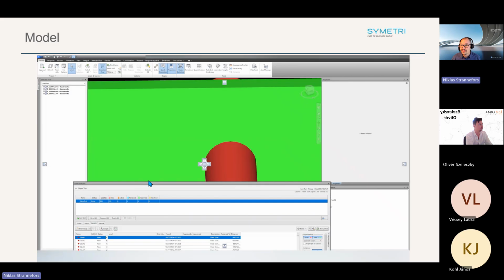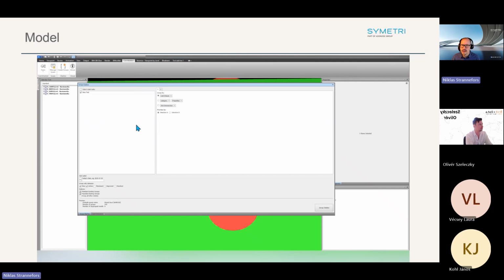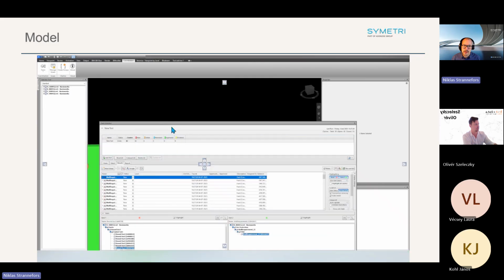I found 259 clashes, penetrations of all these ones. But as you can see, it's kind of ridiculous how you see those, because they are one by one. So what we can do is start grouping these, at least what I did, per wall compartment, per wall that you have. So we went from 260 to 40 different clashes.